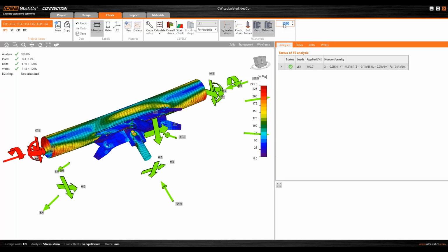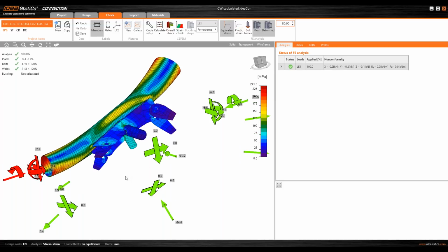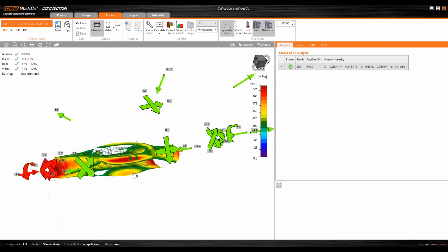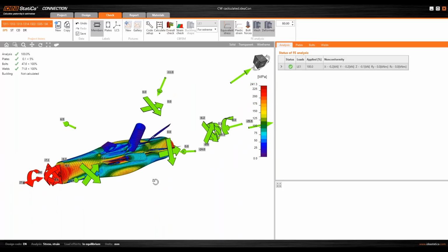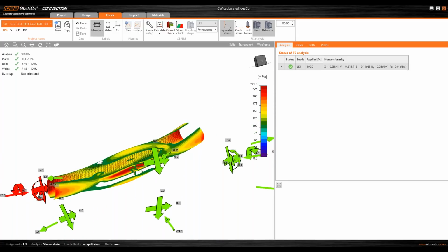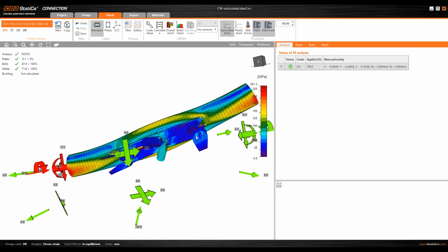And if I scale here the deformation by 80 times more than it is in reality, we can see the deformed shape and have a, let's say, a simple visual check if everything is going all right or the way we would expect. So this is probably working well.